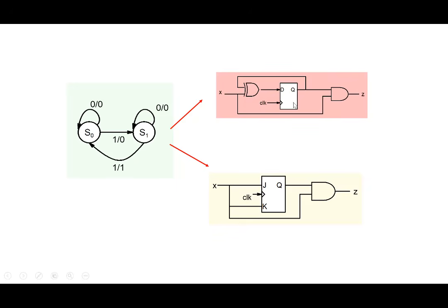Note that a D flip-flop may also be simpler in design as compared to a JK flip-flop, and so we'll not get into the details of that. Often in the problems that will be given to you, it would be specified whether you should use a D flip-flop or a JK flip-flop. But what we are trying to point out is the choice of the flip-flop does affect the complexity of the circuit.